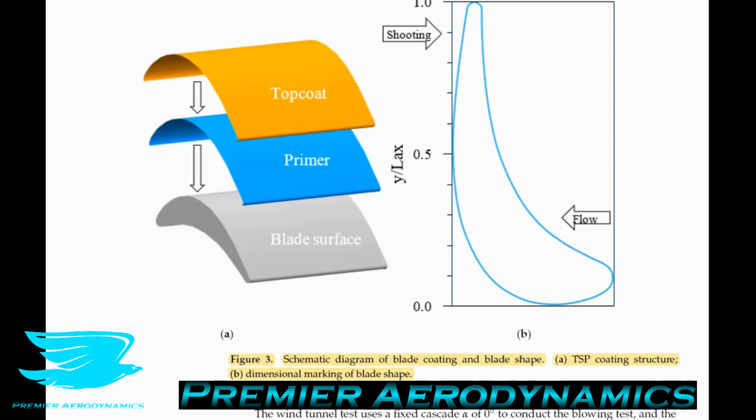And you can use different grade sandpaper, so different grits, like 40, 80, up to 2000 or something, to get it really smooth. And that's what they're doing here. They're sanding it down to make it very smooth so that you won't have this surface roughness changing the boundary layer very artificially. And this is important when we come to CFD, because when we do CFD, we often don't take into account the roughness of a surface.